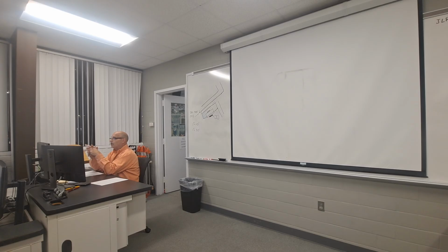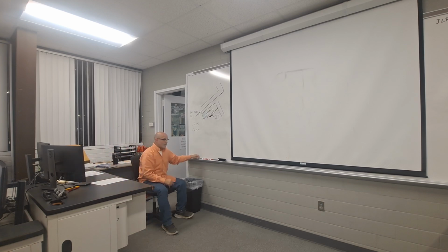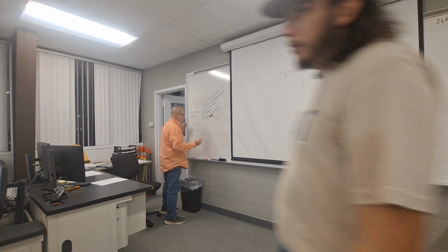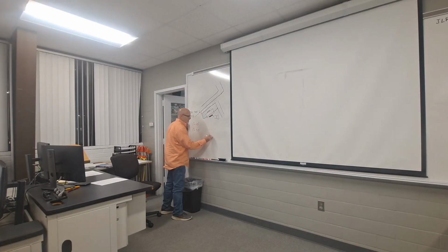You will have 2 rows of bleachers that we talked about, 90 feet long. Your parking lot will be for 100 vehicles, 100 standard vehicles. Now, when you show your parking lot, you're gonna have a property line on the bottom side down here. You're gonna have a road that we're gonna talk about that is outside of it. And then you're gonna have that easement, 15 feet all the way around your property line on the inside, that you're not gonna encroach on.